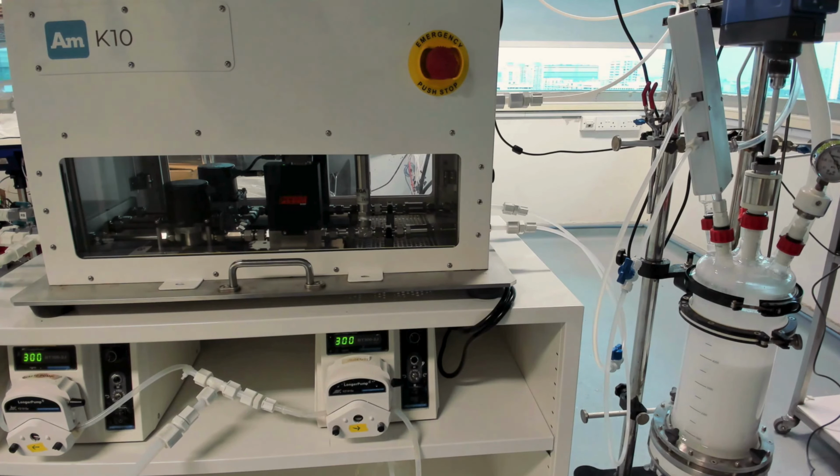And following this reaction, all you need to do is just to take out the reagent lines, put them into a suitable cleaning solvent. This could be acid or water, and run the pump for a few minutes, and it will be ready to go to do the next reaction. And it's as easy as that.